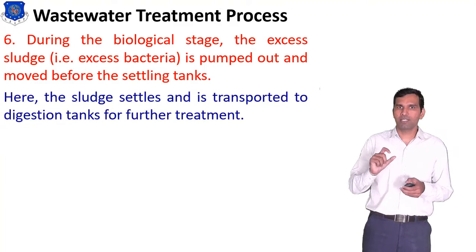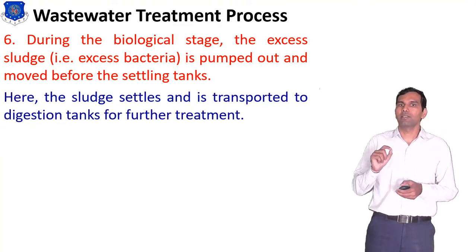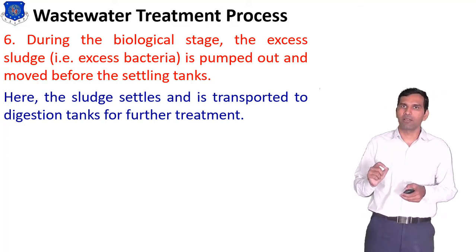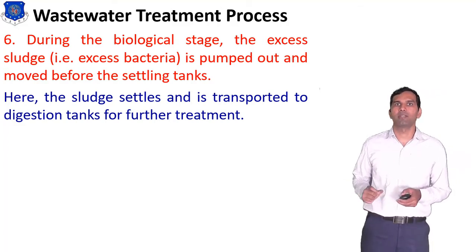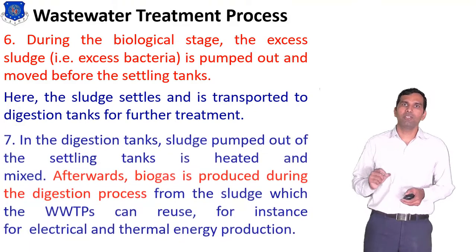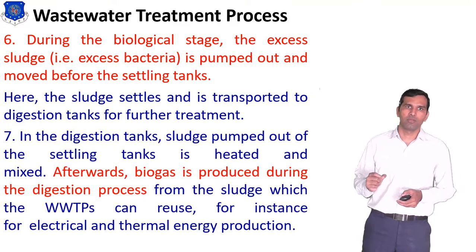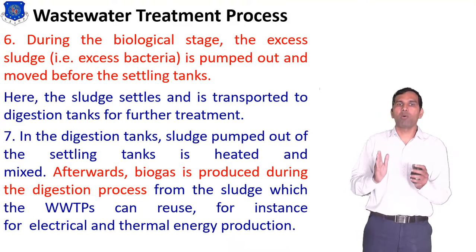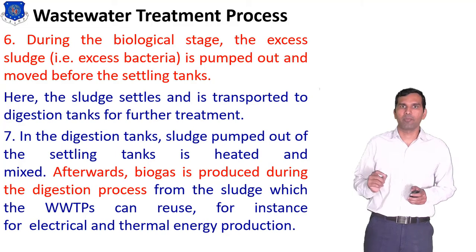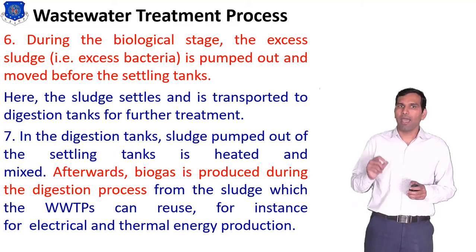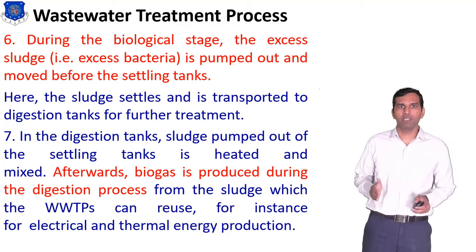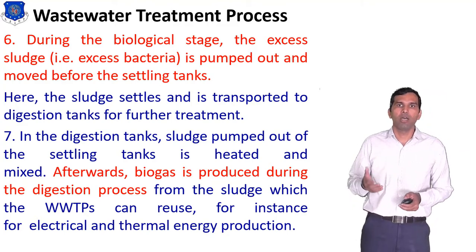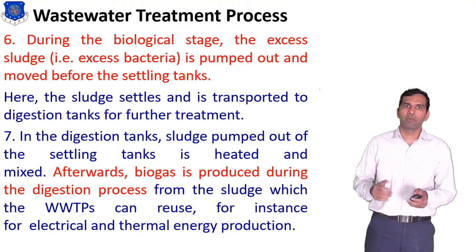Here the sludge settles and is transported to the digestion tank for further treatment. Then we start the next stage. In the digestion tank, the sludge pumped out of the settling tank is heated and mixed. That means in this stage we increase the temperature, and afterward we mix.